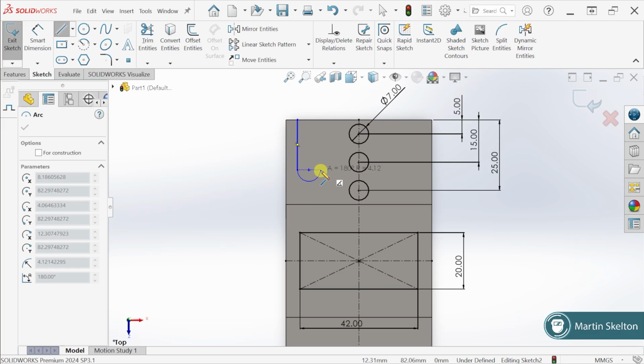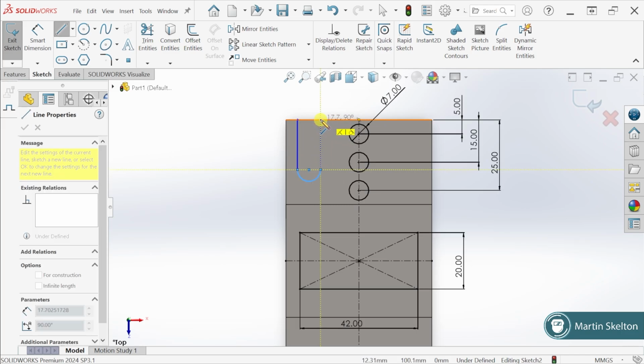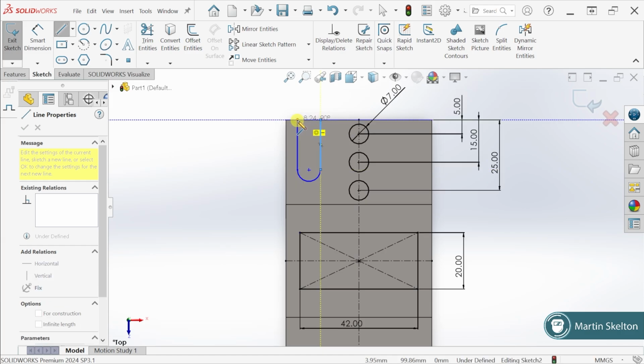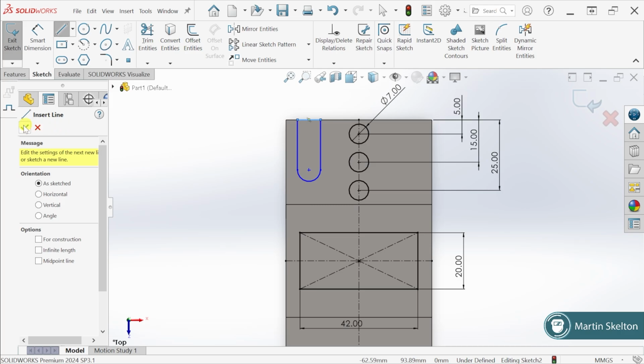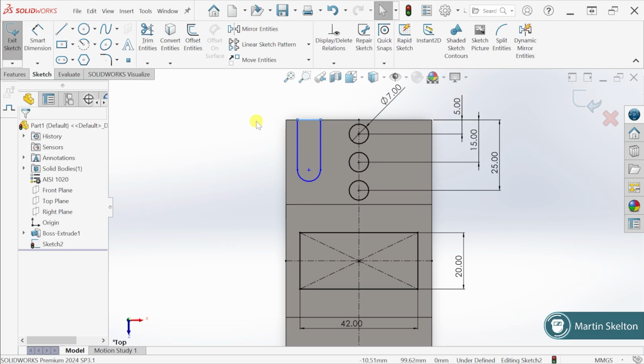If you draw a straight line, travel back to the end of the line, touch the end of the line, don't click, just touch it, and move forward again, it gives you an arc. And then back up. Once we go back up, go back to the point that we started at. And now we have a contour. You can see that contour is just that shape.